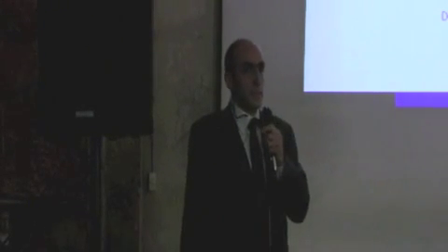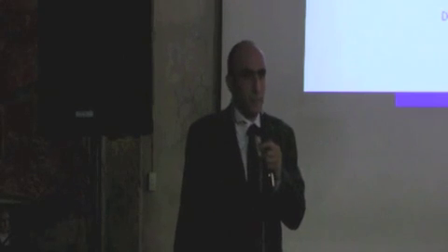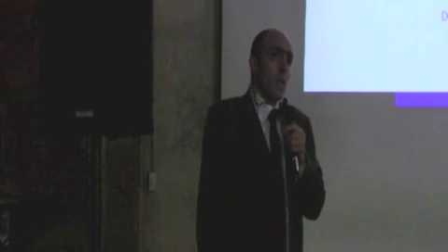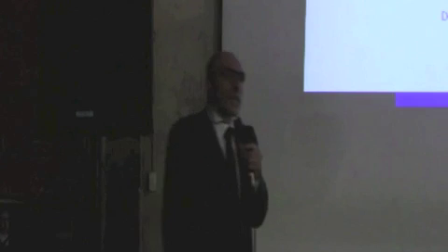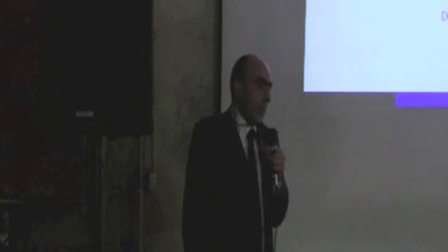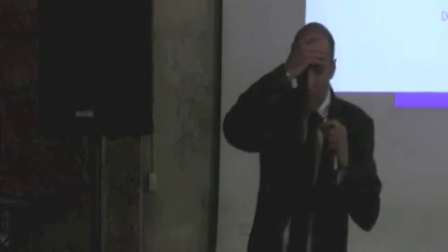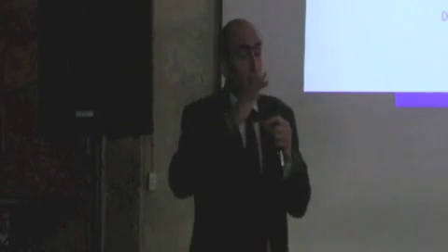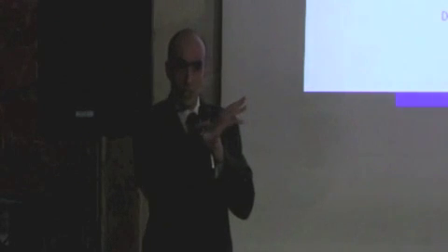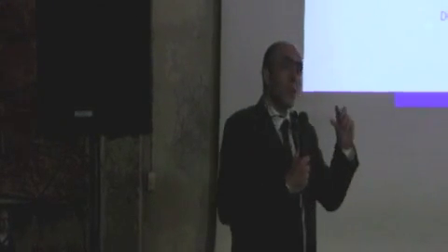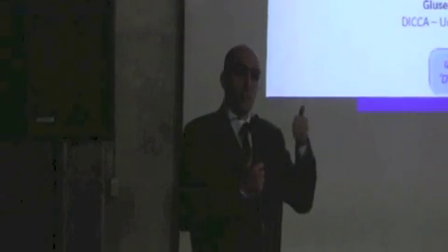What is the sensitivity of the response to the damping that you introduced? The damping is important. We have considered in particular damping which is typical for this kind of structures, but as you can see, we have considered also damping as a bifurcation parameter.